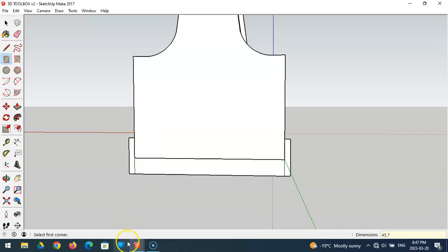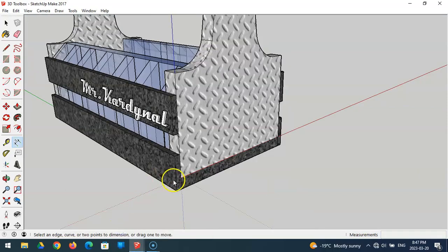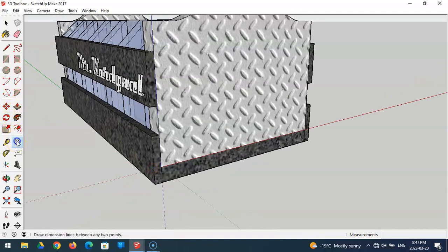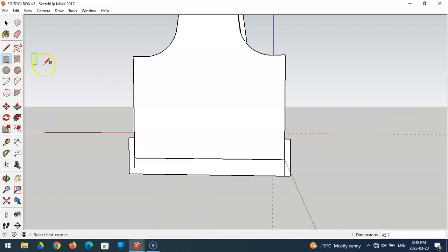Now what I didn't do is I didn't get a measurement in between. So how far are we placing these? From there to there is 26. So in this case we're going to take and draw a line 26 up. I always like to come out and then drop it and type in 26, press enter. And I'm going to purposely draw in so I know where that line is. Actually, I could even draw right to the other side. That would work. And then press escape.